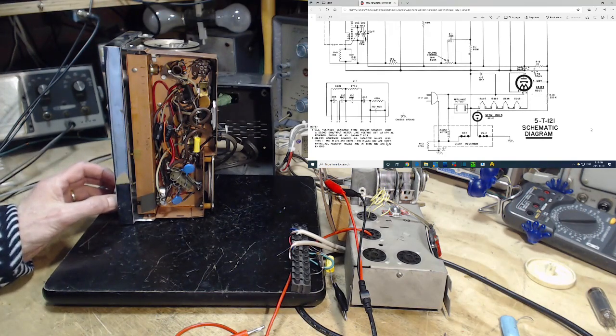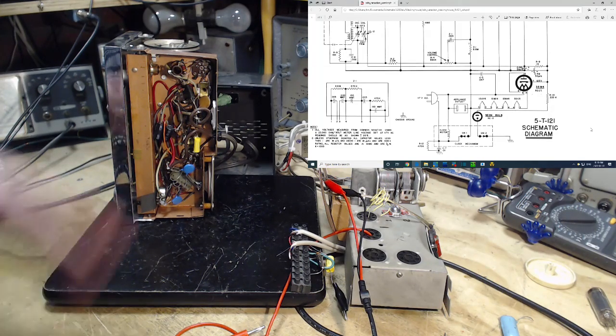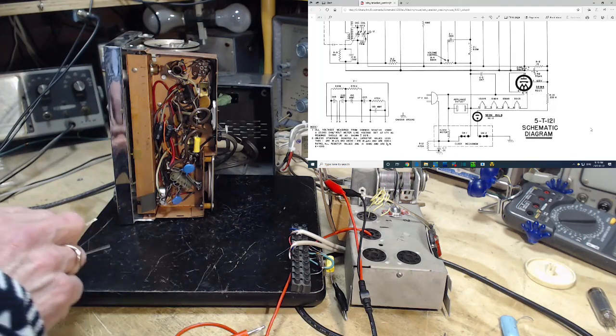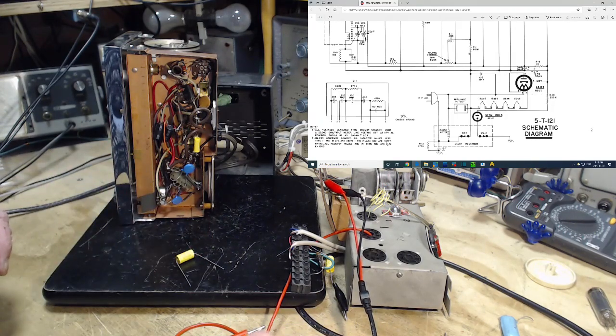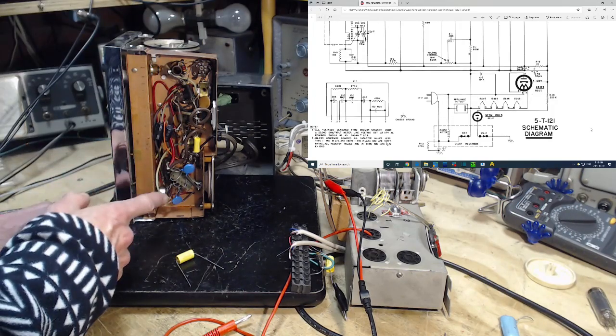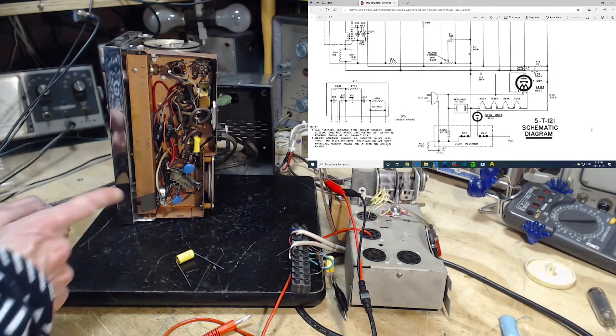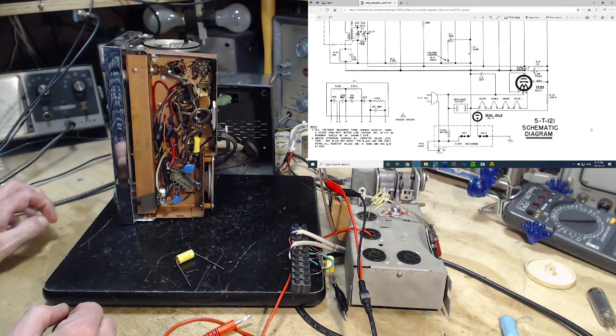Wow, I've never given too much consideration to these capacitors that drain the chassis. Along the way, I've just been doing the usual thing. Now I realize, wow, this is a really, really critical factor. There's a 0.01 in here, which is what the manufacturer calls for. But clearly, a 0.1 is more effective.